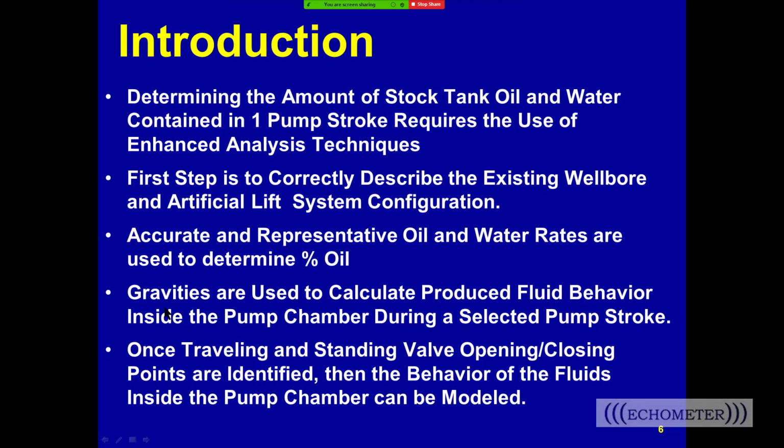oil. The water and the oil gravity are used to determine the discharge pressure and properties. The oil gravity is used to determine things like oil solubility at temperature. So the gravities are important to be entered into the software. Now the gas gravity comes from a flowable shot, if you shoot a flowable, or basically that's where it comes from. And I'm not sure, but we probably default it to 0.7 if there's not a flowable shot.